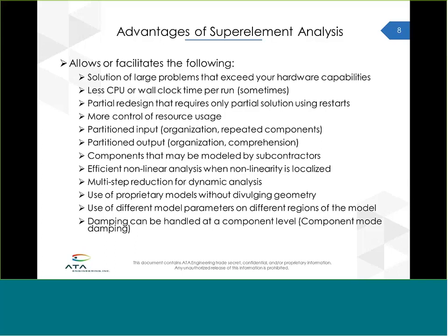because you don't have to run the whole model simultaneously. There are ways that you can have partitioned input and output, so that makes for, if you have repeated components, or just to simplify the process of combining models together and then looking at the outputs, that can be beneficial. If you're in a situation where you have a dispersed modeling environment where lots of different people are developing models, ultimately, someone has to combine all of those, and there are methods within superelements that can make that quite a bit easier, and just with managing all those dispersed models.